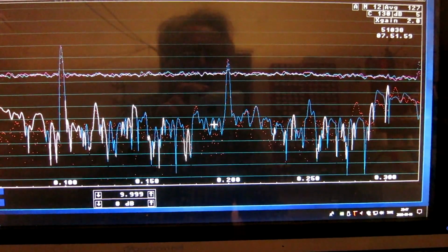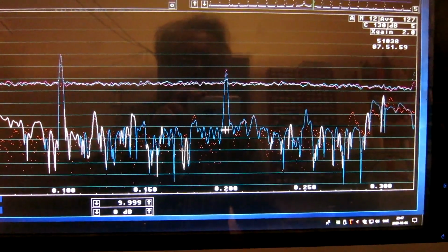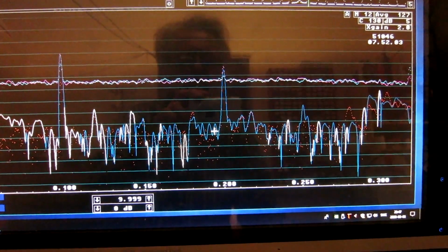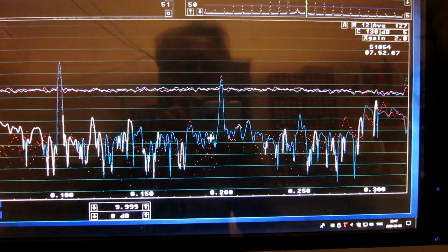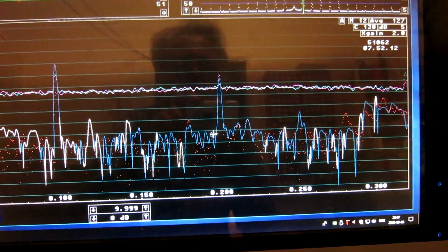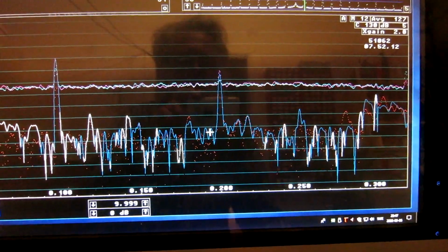And that is because the impedance of the signal source, the impedance at the output of the limiter, is probably very low. It's a square wave and the amplitude will not change if I change the load. So there isn't noise on it.